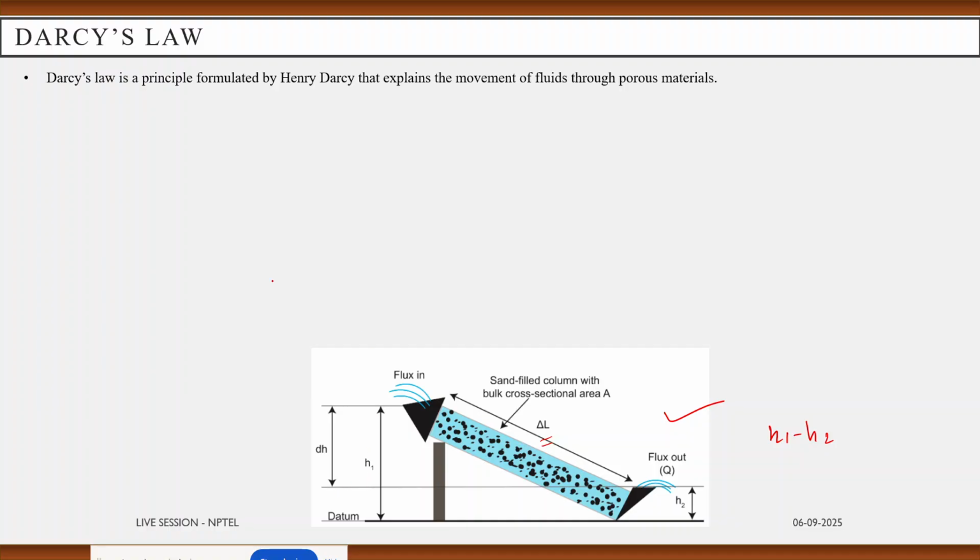So Darcy's law is applied for movement of the fluids through the porous material that we are dealing here. The pressure drop del P per unit length of the bed, that is L, is proportional to the superficial velocity u0. Now you have to remember that superficial fluid velocity is the empty bed fluid velocity. That is nothing but the velocity inside the reactor when there is no bed material. Now this del P by L is proportional to superficial fluid velocity.